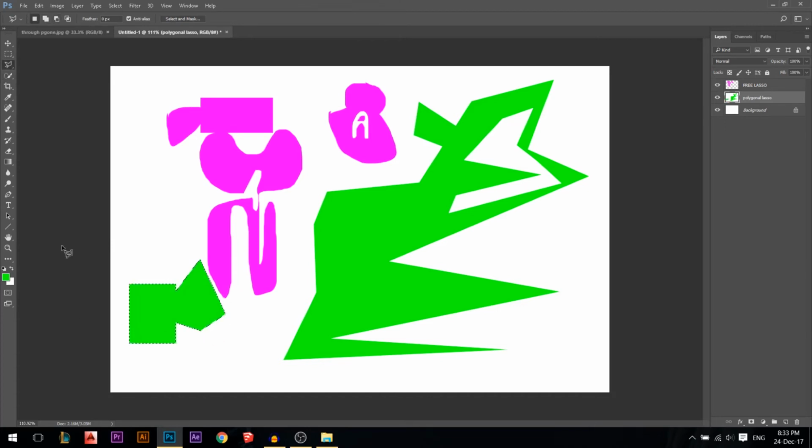Then you will color. Then you can make a new selection here in the middle. And then color this with Control Backspace, which is the opposite. The white, which is the background color. Then Control D to get rid of the selection. Make sure you always press Control D after every selection to get rid of the selection. And if you want to bring your selection back, you press Control Z, it will bring it back.